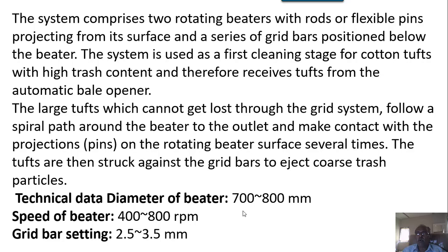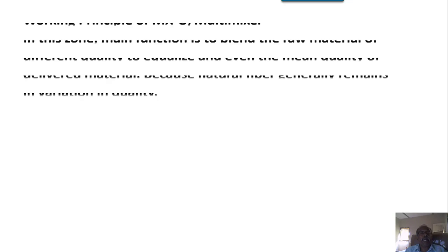Residence time of cotton in the sense how long the cotton will remain in contact with the beater and it will perform its action. So that residence time will govern everything, how far that cotton undergoes that particular given treatment is decided by that. Yes. So we'll go to the next.